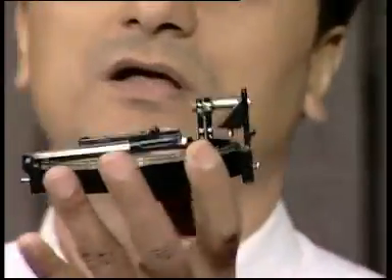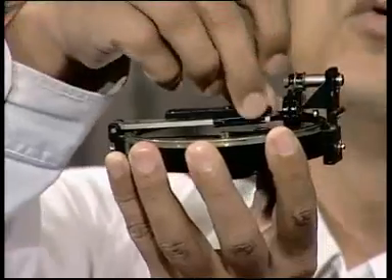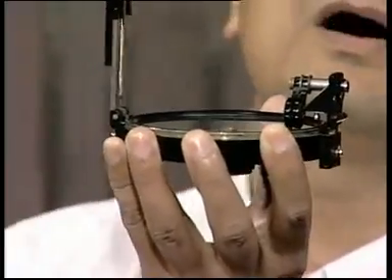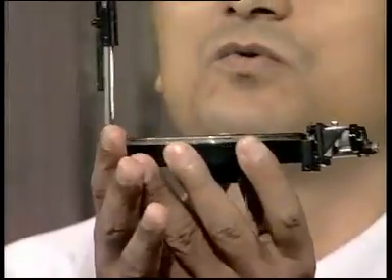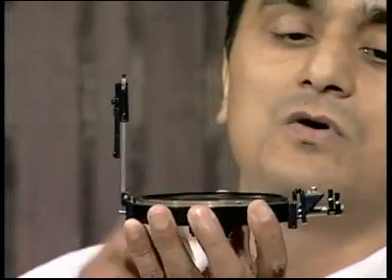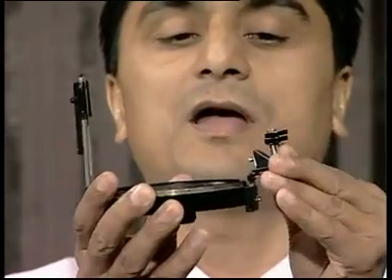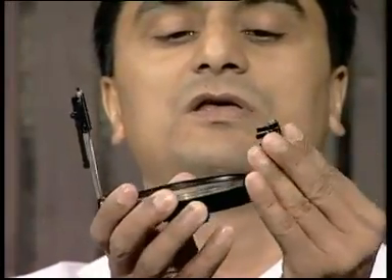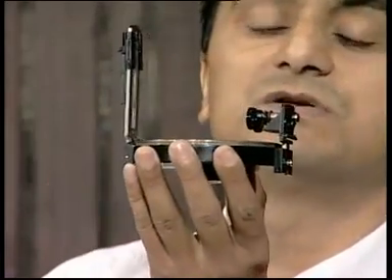The prismatic compass comes in a cover. When you open it, it will be clamped like this. What I can do here, I can open the vane number 1 and number 2 here. Now this is ready for taking the observations. We will see the various parts of it, what they are, what they do. Over here, I can tilt it up and keep it on top of the circle. Now this is absolutely ready for taking the measurements.